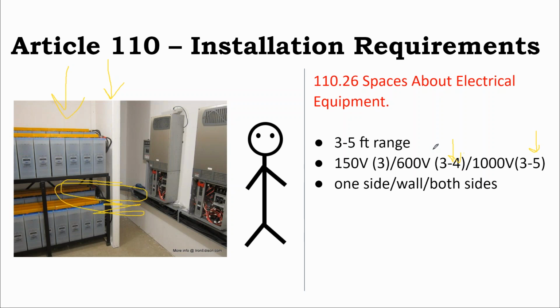And so when I'm thinking about code and electrical room planning, I'm thinking about what the spaces are between the equipment. If we have a piece of floor mounted equipment and another piece of floor mounted equipment, you would need 4 feet of space between the two pieces of equipment, because that's driven by the early sections of the National Electric Code.